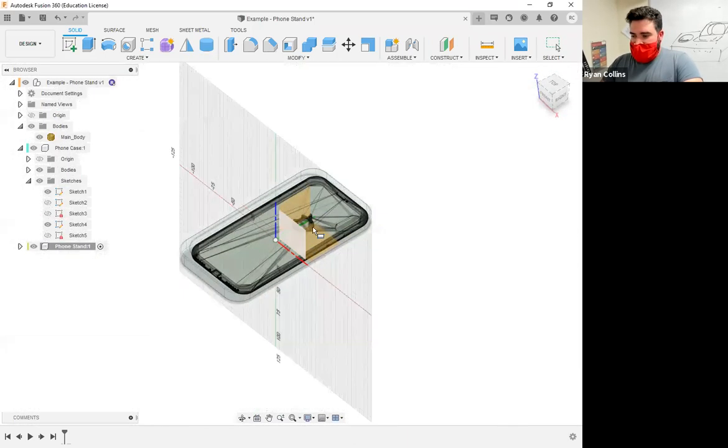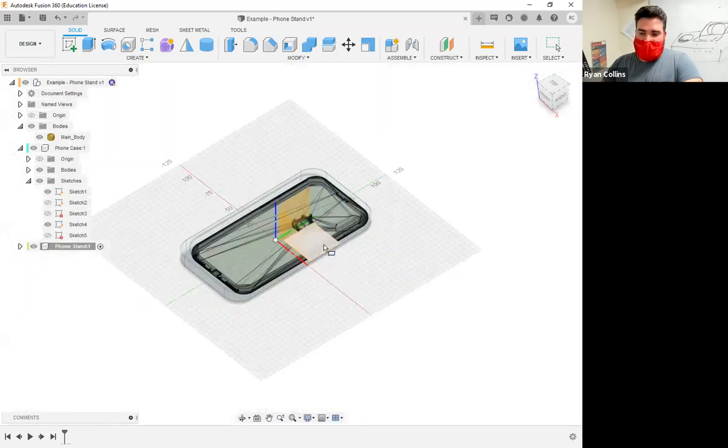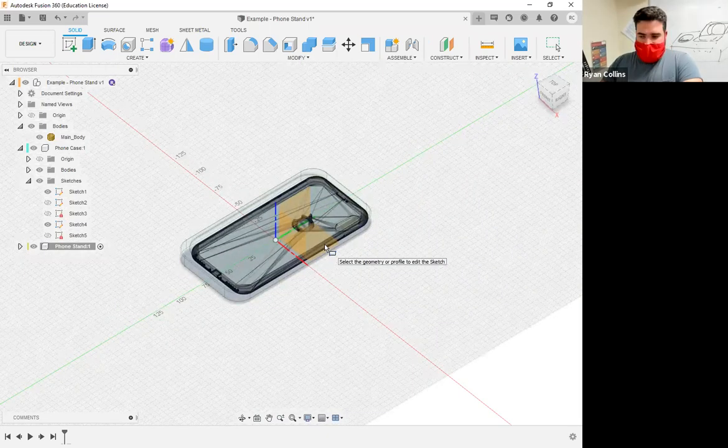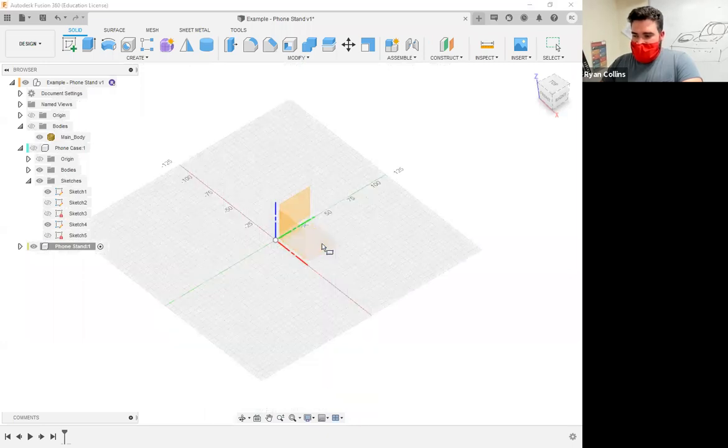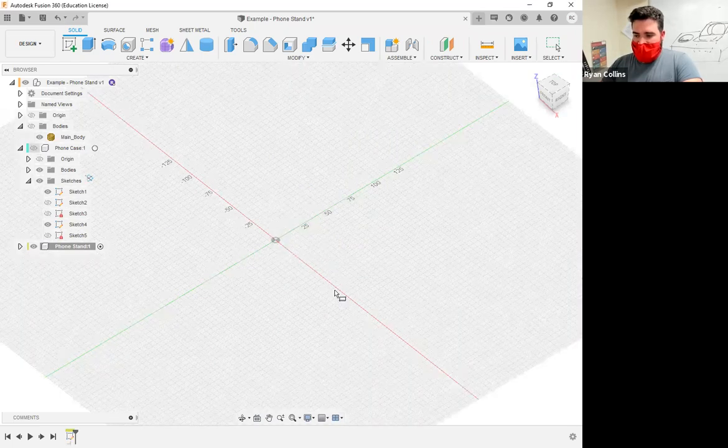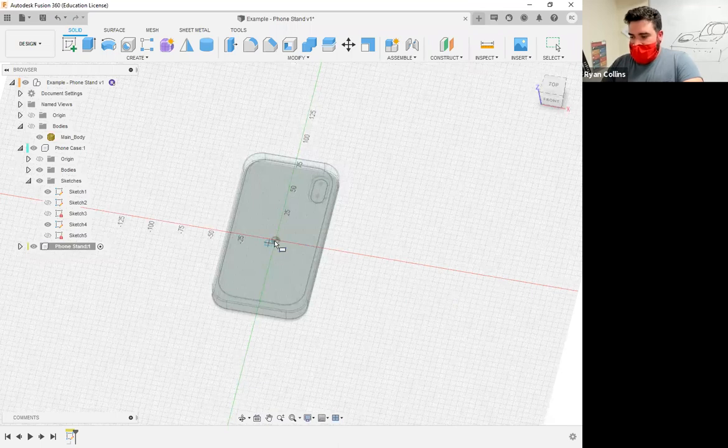Now this sometimes happens, I can't actually get to the actual origin plane. So from there, just go and hide whatever body is in the way, select that, now I can unhide, and I can see what the heck I'm doing there. All right, starting point.